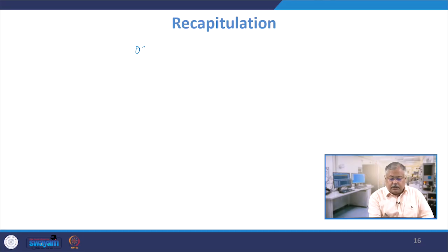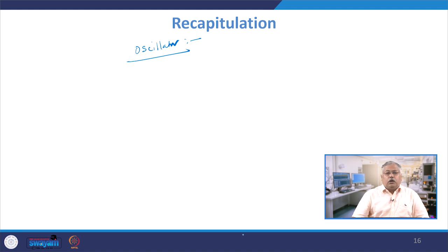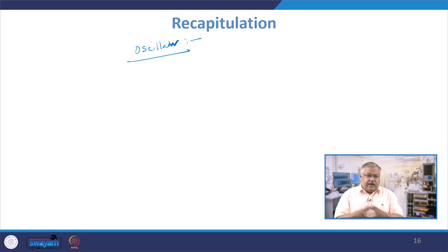We looked into the concept of cryo oscillators. We looked into oscillators here, right. And then after looking into oscillators, we went into the domain of what the challenges of oscillators are at room temperature and at cryo temperature. We looked into a basic structure of an oscillator at cryo temperature, and that was primarily a D2 oscillator. After looking into that, we went ahead and discussed the functionality of it and how to reduce the phase noise at such a low temperature.